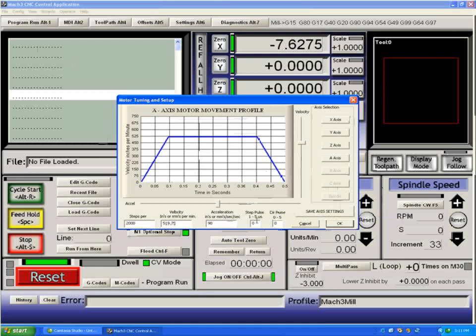If for whatever reason you find that your motors are not moving when you're using your up and down arrow keys, or they sound bad, you can use these numbers to increase between 0 and 5 the step pulse width or the direction pulse width. The only time you'll change a direction pulse width is if you find that you're losing one step each time you change direction. For 99% of users, you will never change this above 0. For 90% of users, you will never increase the step pulse above 0.